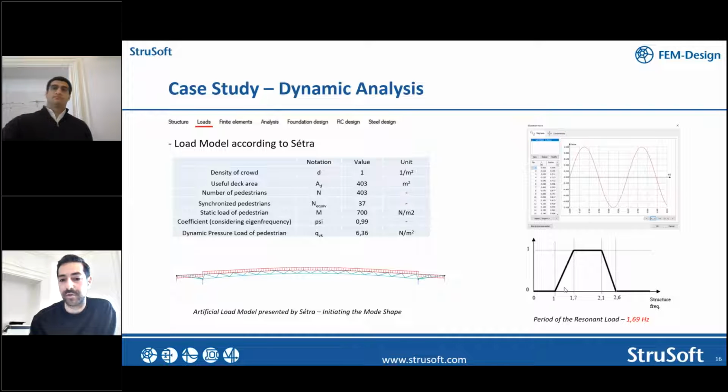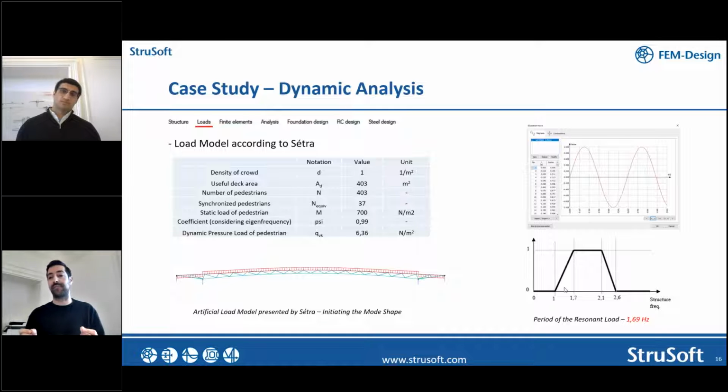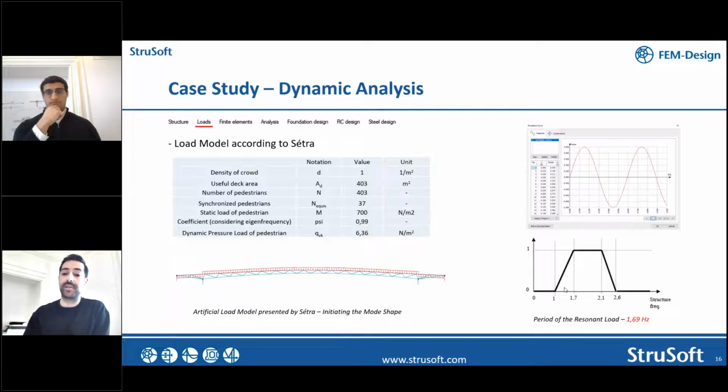This is actually where, as a design engineer, you can use the existing guidelines to manipulate your result, if you can ensure that your boundary conditions are acting as you want them to. So if you would have a very good roller that would not give you any longitudinal stiffness, you could basically decrease the dynamic load case in this one.